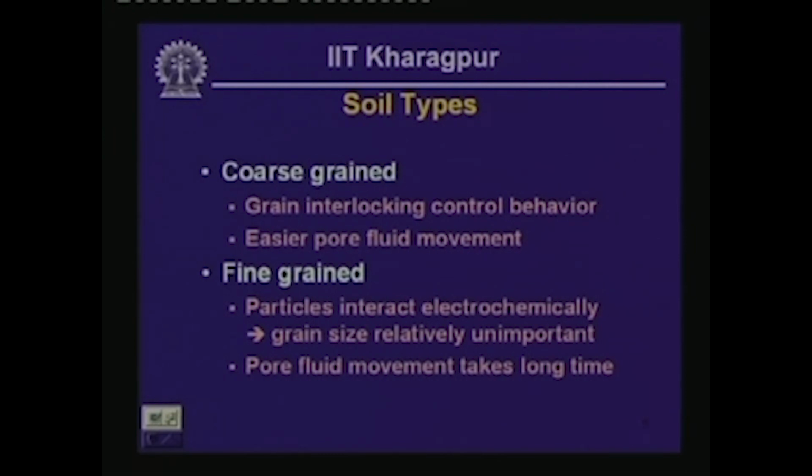Now, what was also evident from what we discussed in the previous slide with the 3 photographs is that there is an essential difference in the physical characteristics of the particles of coarse grained soils such as sand and fine grained soils such as clay. Whereas sands are composed of roundish or block like particles, clays are typically composed of plate like particles, or in some cases they are composed of thread like material.